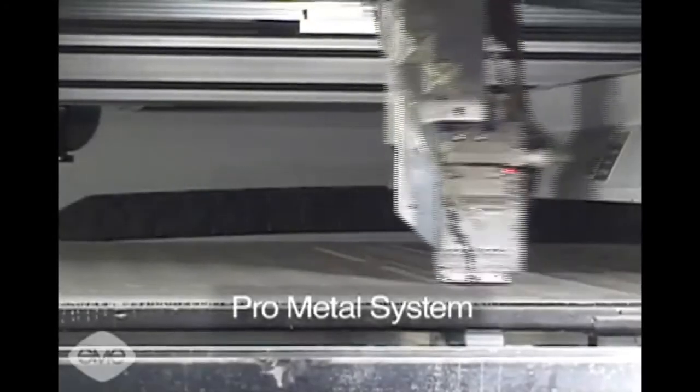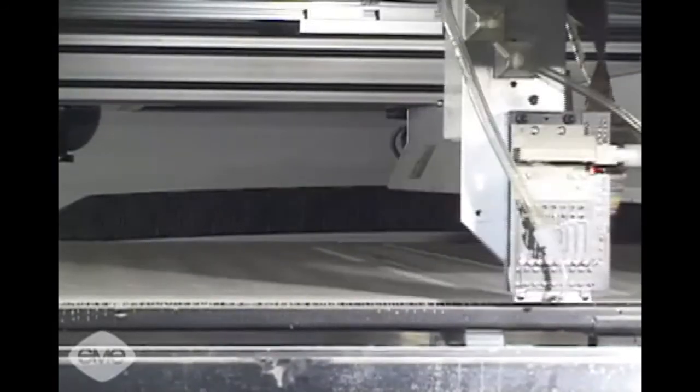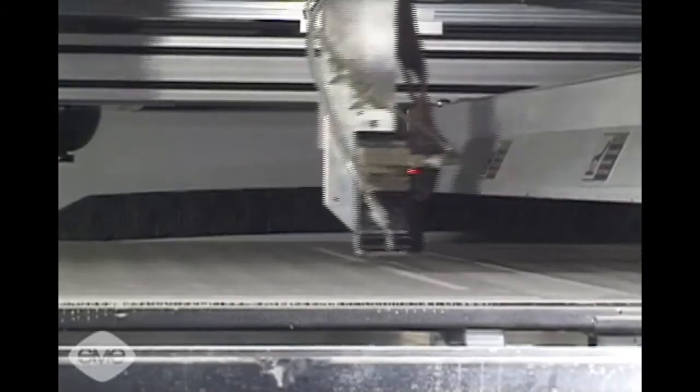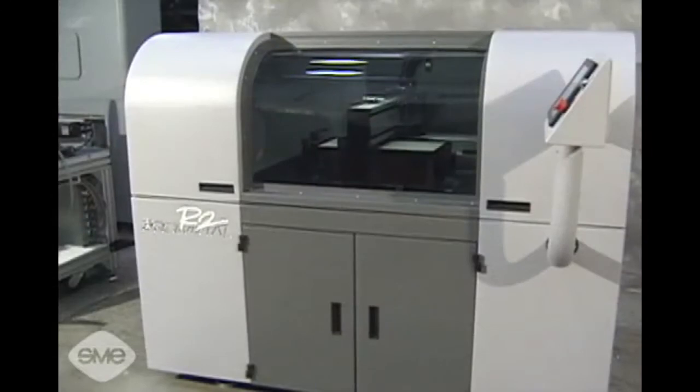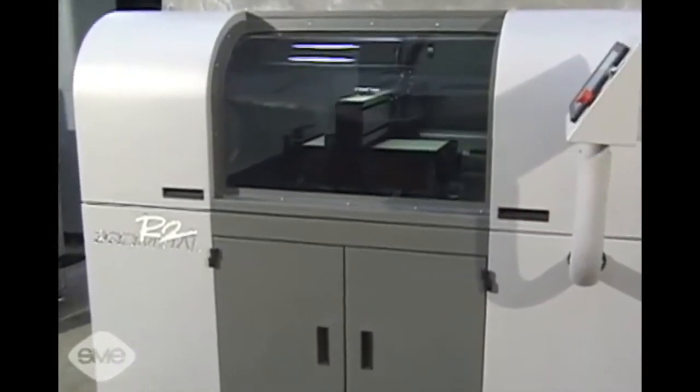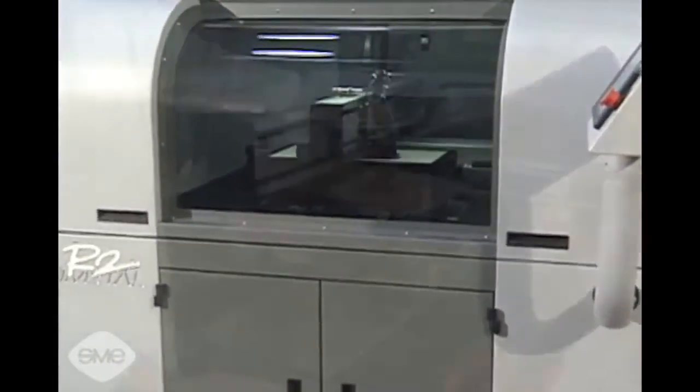The ProMetal System modelers are also used for creating metal models. This system involves using inkjets to apply a liquid polymeric binder onto powder media to produce models. The models are built from steel-based powder from the bottom up.